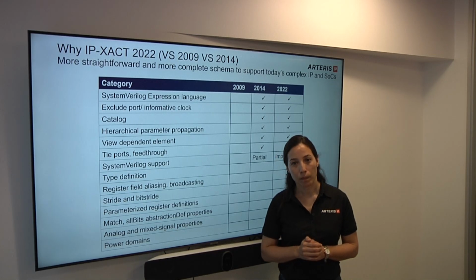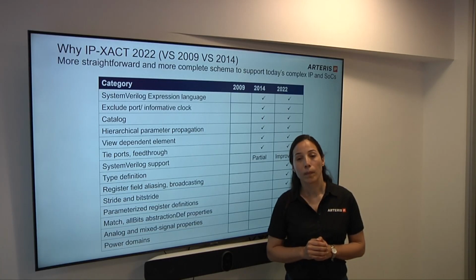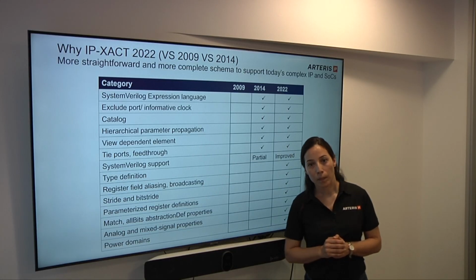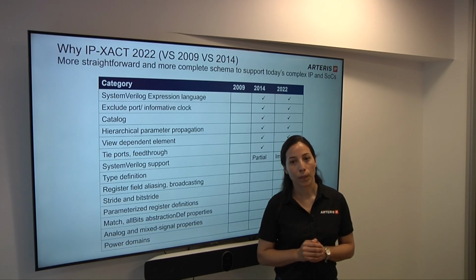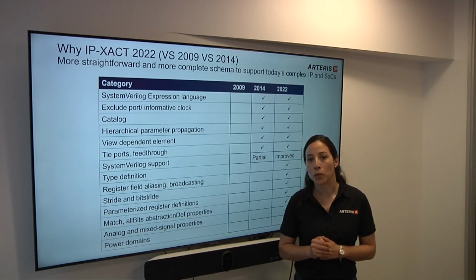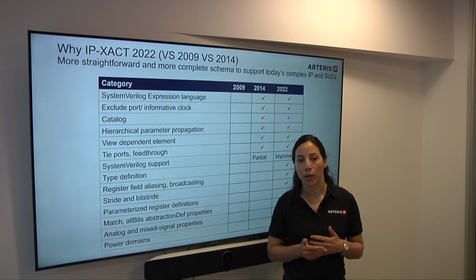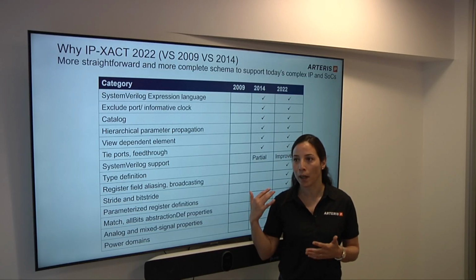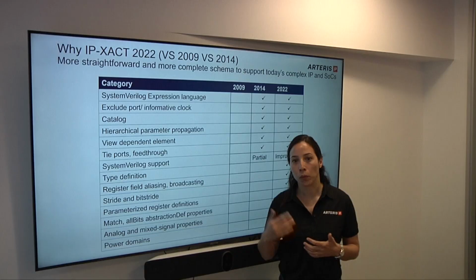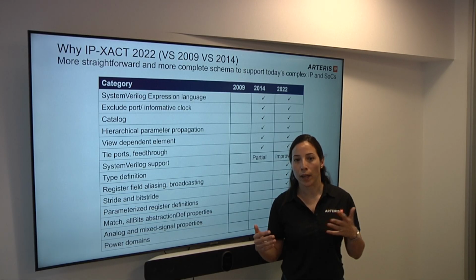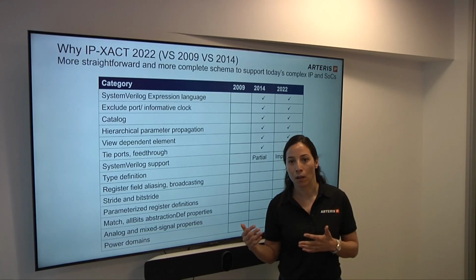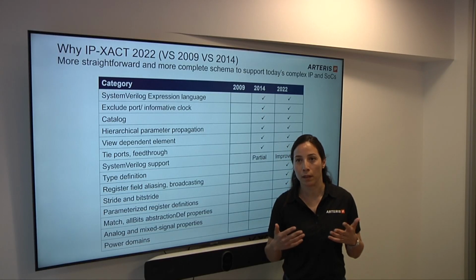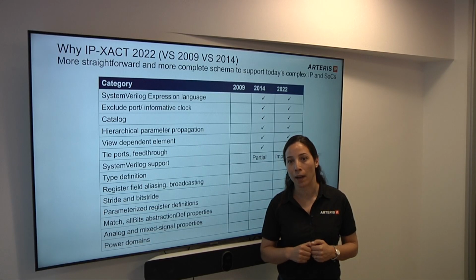But you may have multiple NOCs in one of these as well, right? It may not just be one, because you've got GALS, globally asynchronous, locally synchronous. You may have to move data in different directions. Right, that's true. You can have multi-NOC, you can have a composition of NOCs. These are problems that we already handle with our solution, so you can still connect these NOCs all together and very easily create your system at a high level.